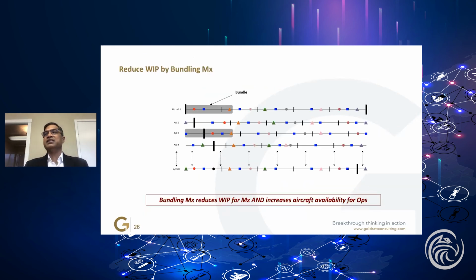The idea behind bundling is not very new, but how can we do bundling in a structured process? So what you do, anytime an aircraft comes down for a scheduled maintenance activity, you look ahead 30 days, 20 days, whatever, and there is a science behind this. Applying very simple math, we can decide how many days we can bundle ahead and pull in all those tasks and do it together. And now, instead of bringing the aircraft multiple times, you bring it only once, focus a team, and get it done.